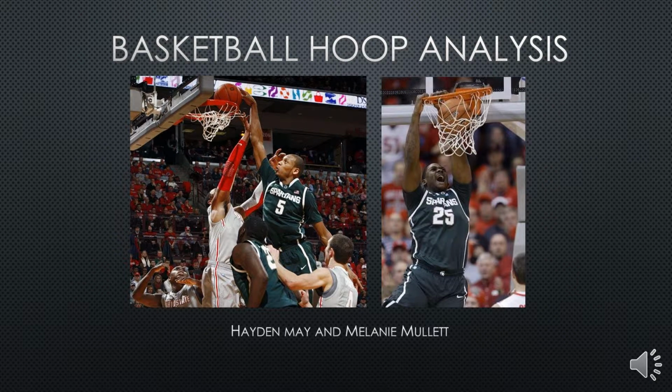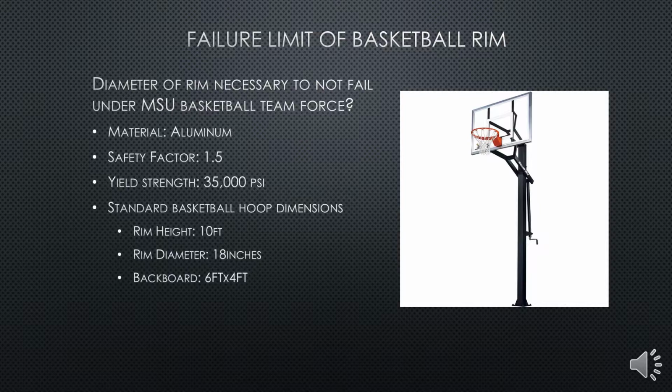I'm Hayden. And I'm Melanie, and we did our analysis on the basketball hoop. Our goal of this project is to determine the failure limit of a basketball rim. The tested basketball hoop is made of aluminum and tested with a safety factor of 1.5.